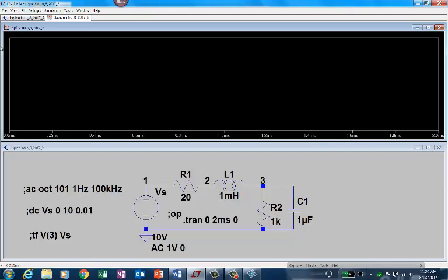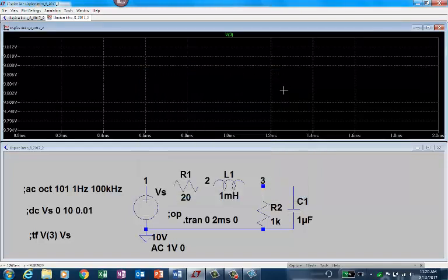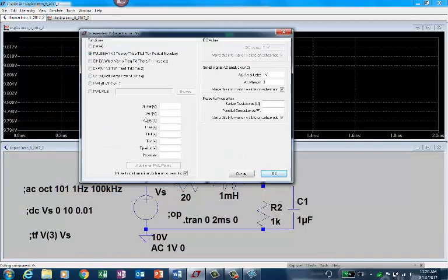We want to see that again. Let me draw the output voltage across V3. No, I didn't set up the transient analysis. I have to go for a pulse. I have to select the pulse, like 1 volt, 0, and then 10 volts, or maybe 1 volt. Then we want to set the rise time to 1 nanosecond and fall time 1 nanosecond, and the delay time is 0.